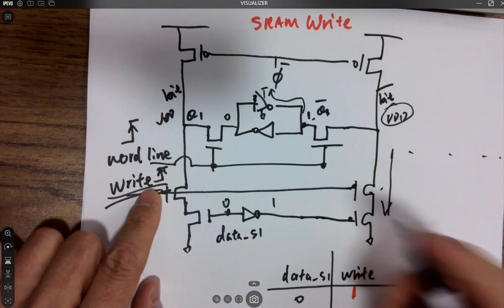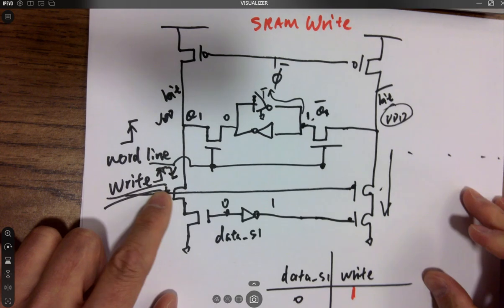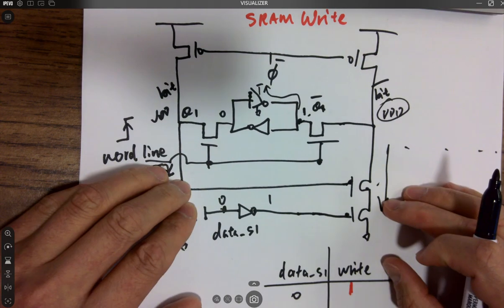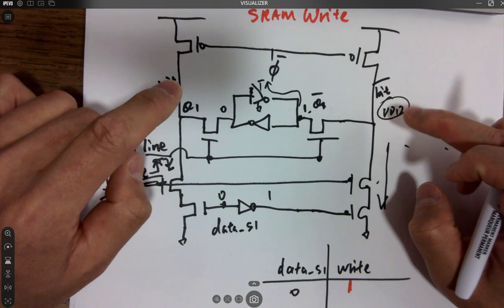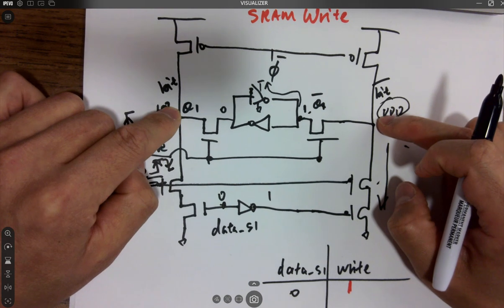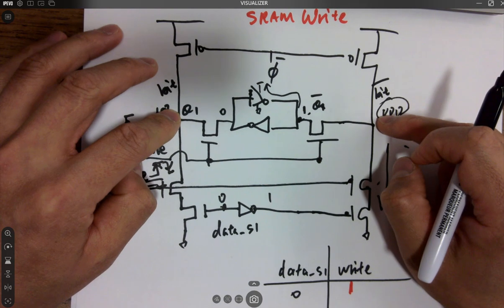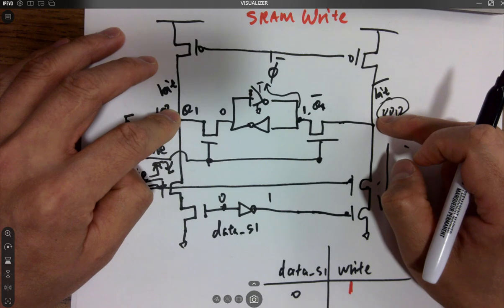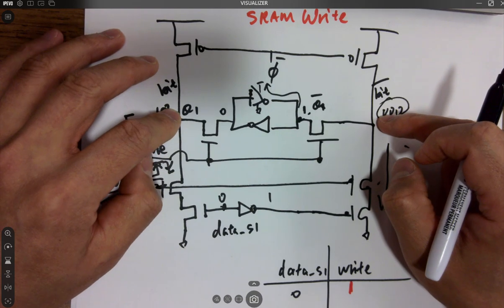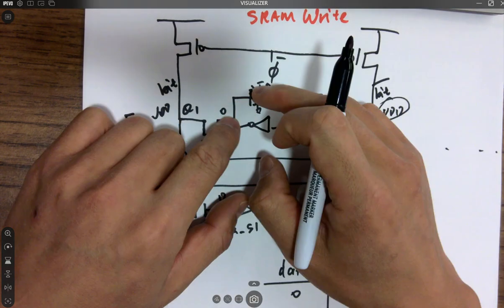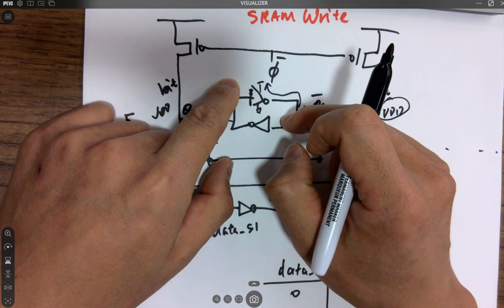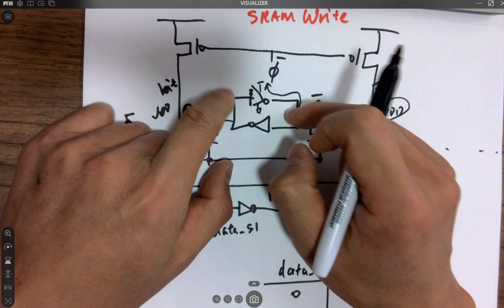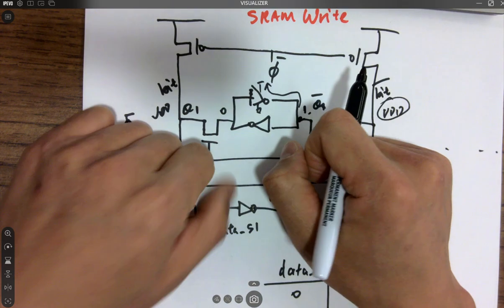And then I can have a floating edge to the right. So this is getting shut off. This becomes floating again. So whenever this is getting floated, which transistor dominates? The latch. The latch dominates. It gives a super strong pull up here, and it's a solid pull up. Start getting a static memory.